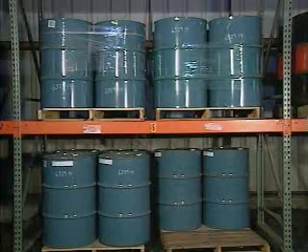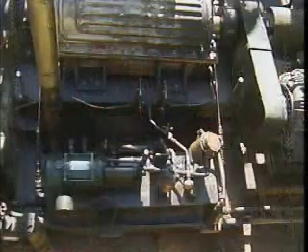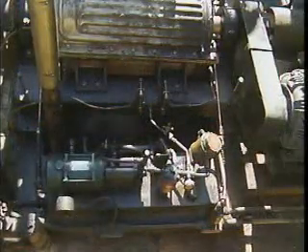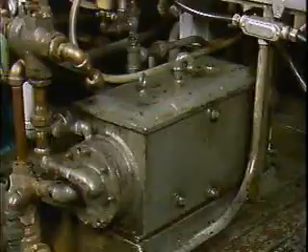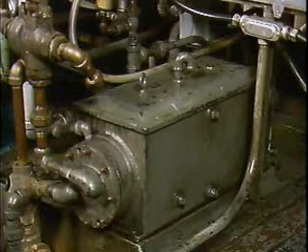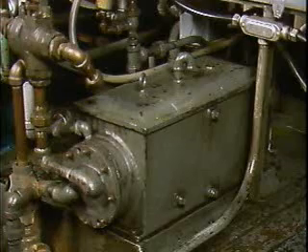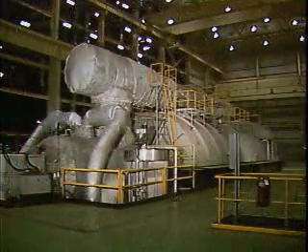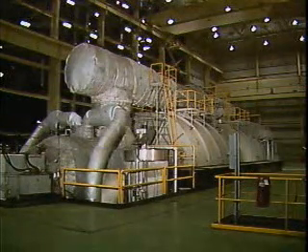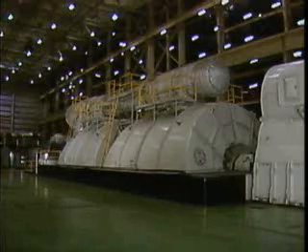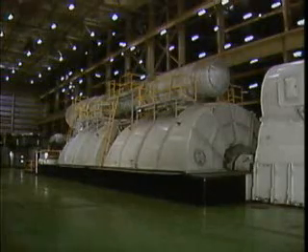One group of oils is circulating oil. Circulating oil flows or circulates through a piping system or moves freely within a closed area. The circulating oil group also includes hydraulic oil. Hydraulic oil is primarily used to transfer force from one component to another in a system. Sometimes, though, the same circulating oil is used for both lubrication and hydraulics. For example, large steam turbines are often built to use the same oil for lubrication and for hydraulic control.